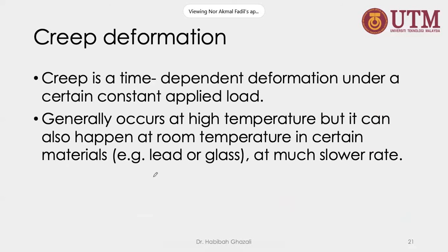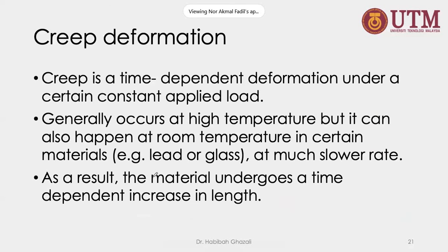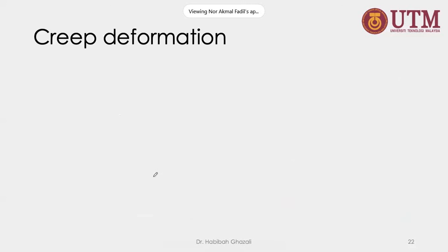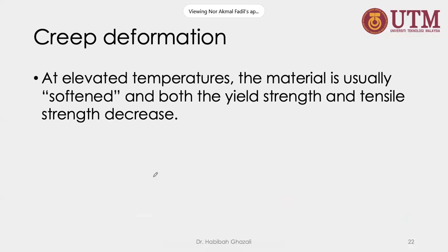So always remember this. There are some other failures, not because of the fatigue, not because of the fracture, but because of the creep. Okay. You only apply a constant load. Okay, but it takes very long. There is some time influence in this failure. Okay, why? Because it may soften, so the tensile strength is not similar anymore. The yield strength is not similar anymore. It may affect their strength.